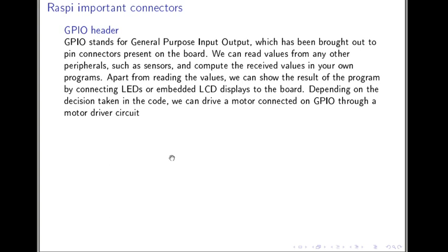The difference, if you want to compare Arduino and Raspberry Pi: Arduino has 6 analog inputs while the Pi has only one. So basically Arduino is more suitable for connecting analog sensors directly. But if your sensor is mains based or uses an SPI or I2C connection protocol, it is better to connect it with the Raspberry Pi directly.